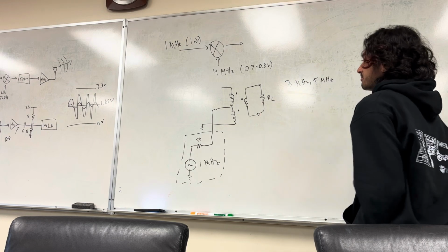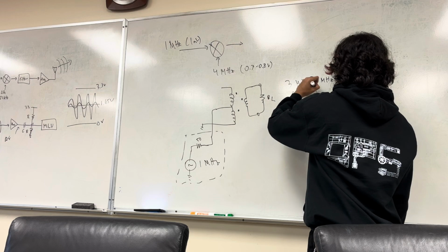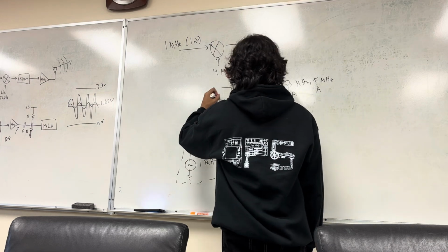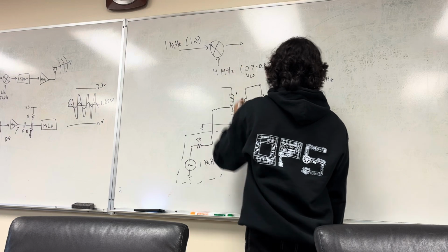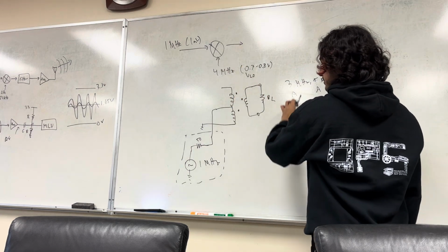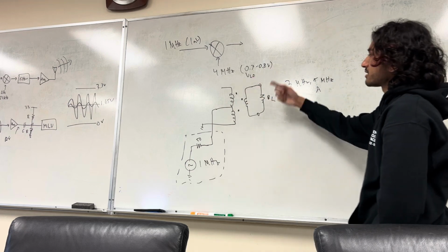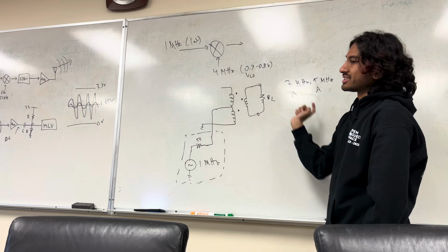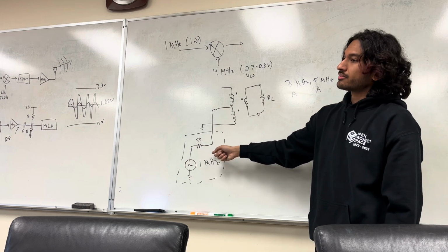And these had some amplitude, right? Let's call it A for now. And then we had our LO amplitude, we can just call this VLO, right? And we saw that some of this is going to leak. So you're going to see some component of your 4 megahertz, 3 megahertz, 5 megahertz at some fractional amounts of these amplitudes show up here.